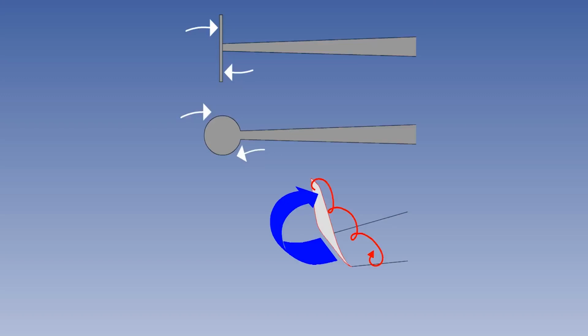Probably the most widely seen method of controlling wingtip vortices is the winglet, which is now incorporated into many categories of aircraft, large and small. Small vertical or near vertical extensions of the wingtip are shaped and angled to the induced airflow, generating a small forward force, or negative drag. Winglets also partly block the flow of air from lower to upper surfaces, reducing the tip vortex strength. The small vortex created by the winglet also interacts with and further reduces the strength of the main vortex. Finally, simpler variations of wingtip shape, such as turned up or turned down tips, can be used to reduce induced drag. Vortices are weakened by the blocking of airflow from lower to upper surface round the wingtips.